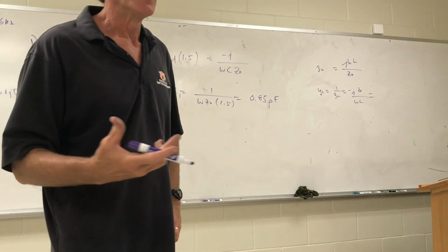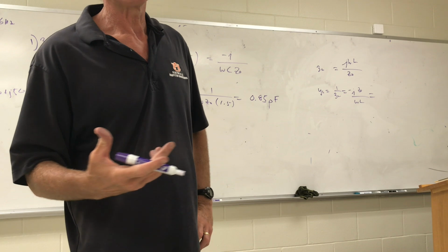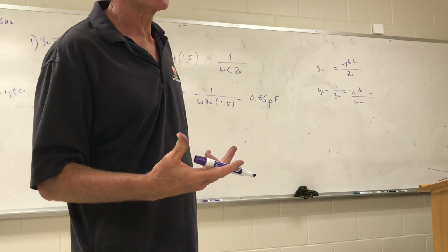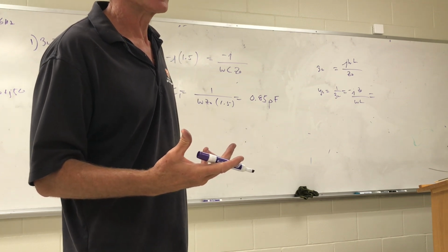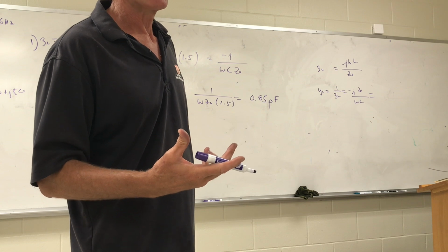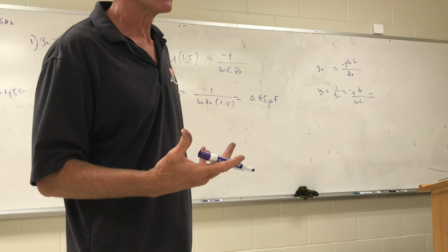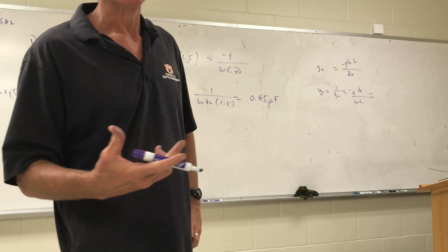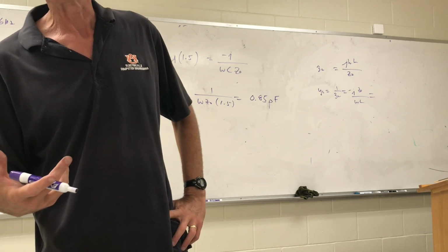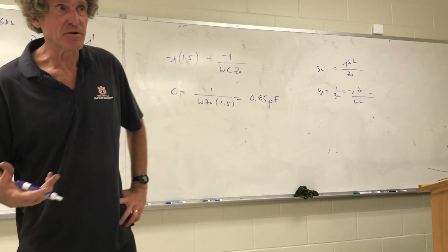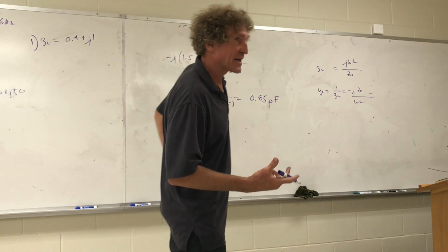If you're going to do any kind of repetitive design work with that, if you've got to bias something in DC, and by the way, in general, capacitors in parallel kill noise. Inductors in parallel look like antennas. It's not quite an antenna, it's a near field coupling device. You don't want that.